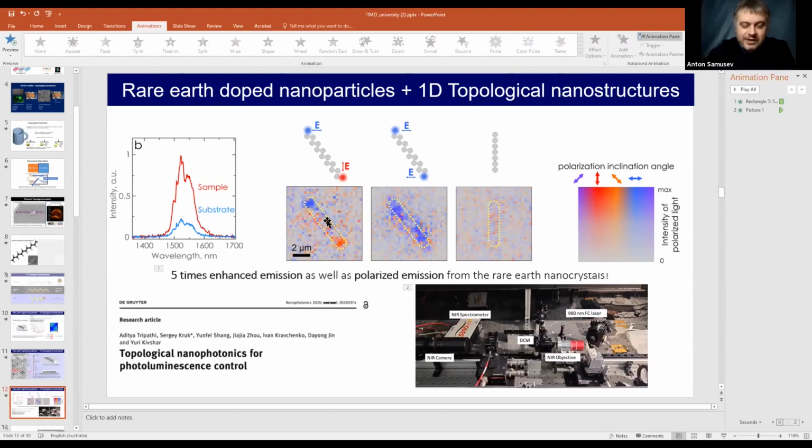I'm just wondering whether it could be an anisotropic Huygens-like nanoantenna, which will provide the Huygens regime along one dimension at the frequency of your interest. Definitely. And that will give you the selectivity in polarization and quite a nice enhancement. Definitely, if you use a single nanoparticle, let's say an ellipsoidal nanoparticle, you can also have a similar effect.